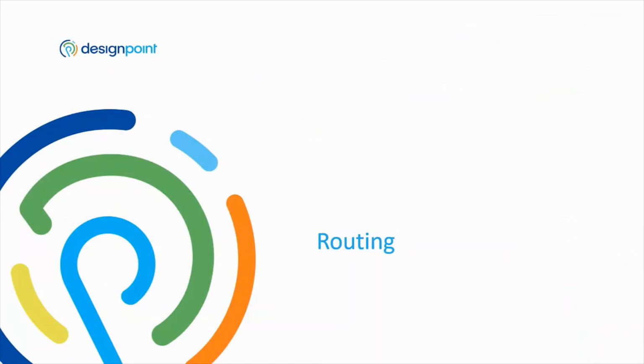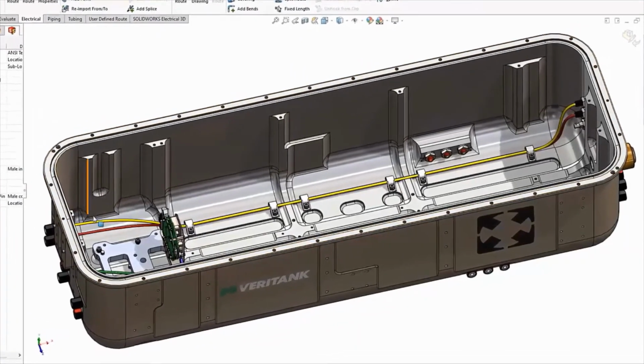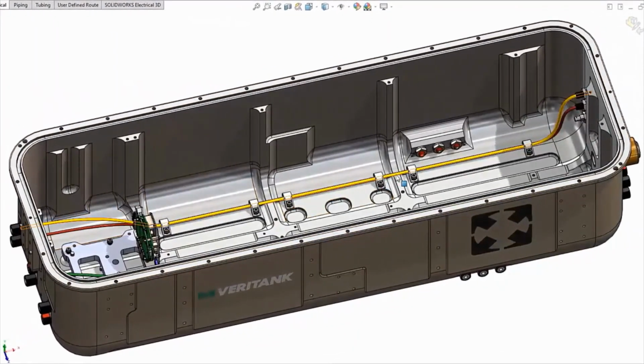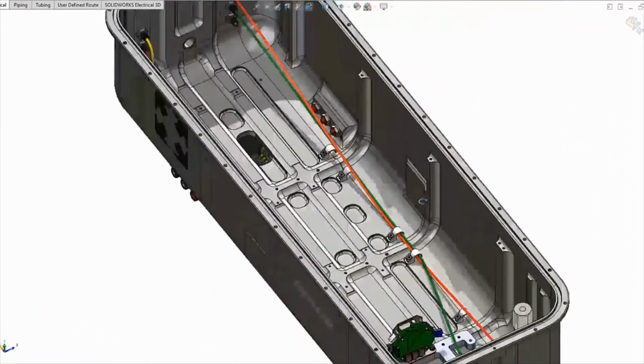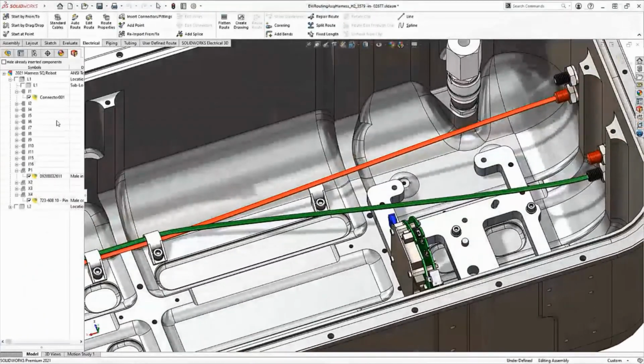We already arranged the yellow and brown wires to go through the clips. However, the red and green wires are only partially secured through a few clips. To finish securing these last 2 wires through clips, let's edit the route. Choose the Route Edit Through Clip tool and then select the axis of the clip and choose the wires you want to route through that clip.